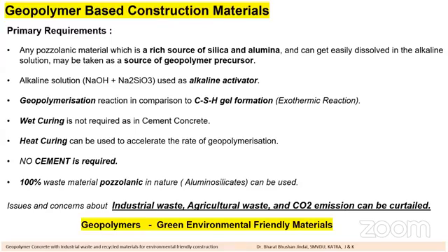you can use 100% rice husk ash or GGBS as a pozzolanic material, which is termed as aluminosilicate material. So what we are doing, the concern which we discussed in the previous slide, that means utilization of waste material, that was one of the concerns that is getting addressed here in the case of geopolymerization.